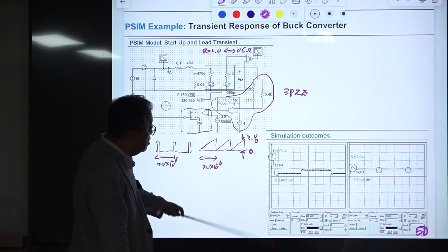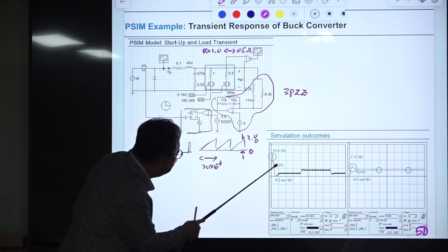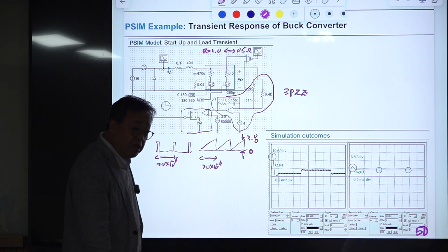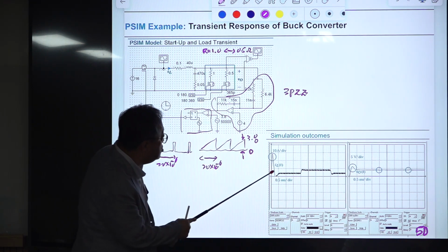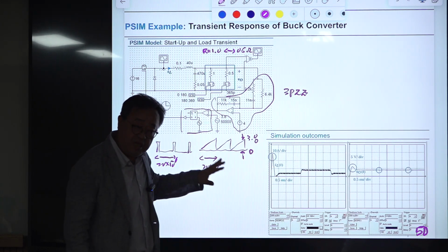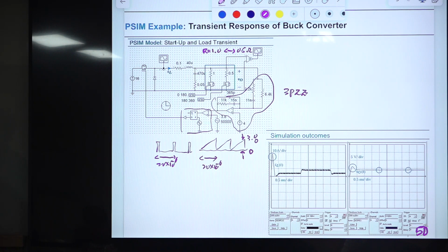I simulated using this. And the initial inductor current is way high. Okay, this is a transient period. There is no soft start scheme. Without soft start, this is very dangerous, and it kills your switches and diode. So during this on-time period, people increase the duty ratio gradually. So the inductor current at the input stage during startup is something like this. This is called soft start. With a soft start scheme, this will be smooth. It doesn't go like this.